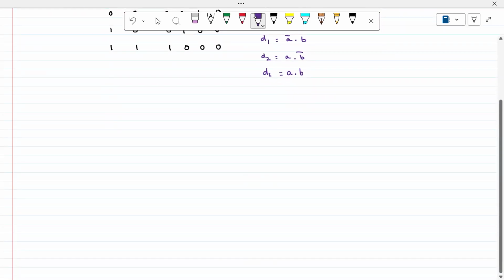Let's start with which one you feel better. It's very easy. Data flow model as usual, because equations are very less, number of variables here we have. So let us go and write that. Okay, let me start the module. What is the name of the module? Let us give decoder DEC. Let me write in lowercase letters, and all the time we don't want to forget that, since it is case sensitive. DEC underscore 2 by 4 underscore DM. DM stands for data flow modeling. That's the identification I have given.